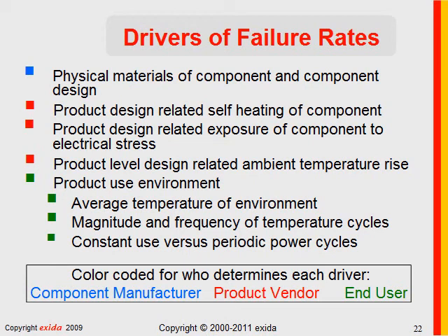What are the drivers of failure rates? Well, absolutely, the physical materials of the component and the component design impact failure rates. The way a component is used in a product, including any self-heating due to power dissipation, the exposure of the component to electrical stress or any environmental stress, and the product level design related to ambient temperature rise, have everything to do with the failure rate of a component.